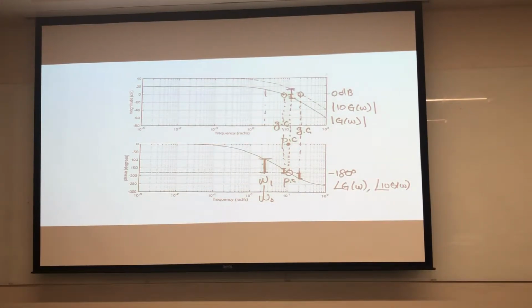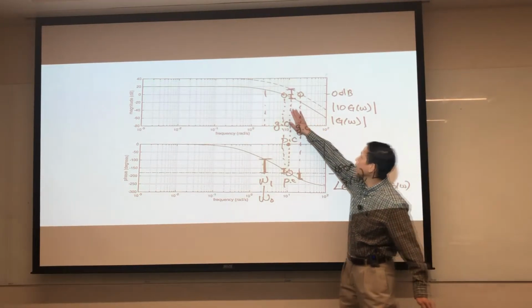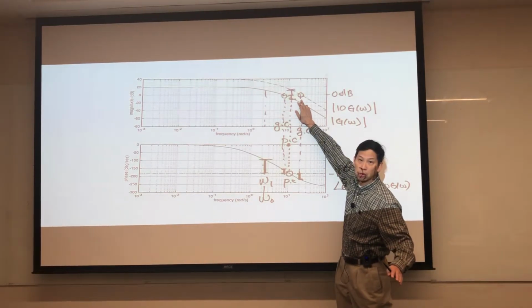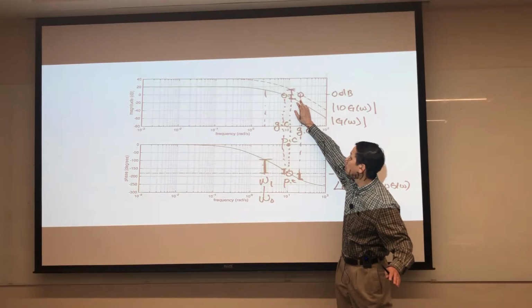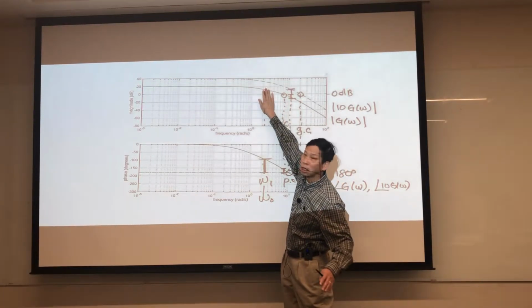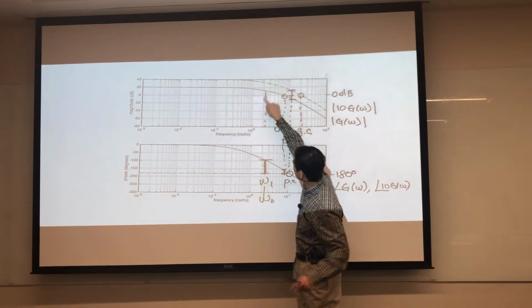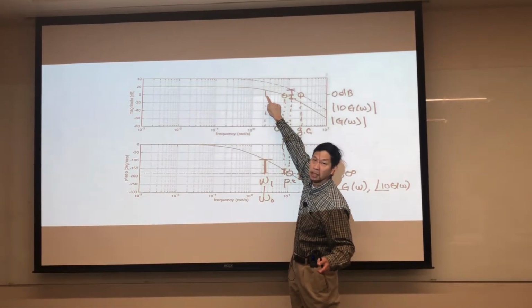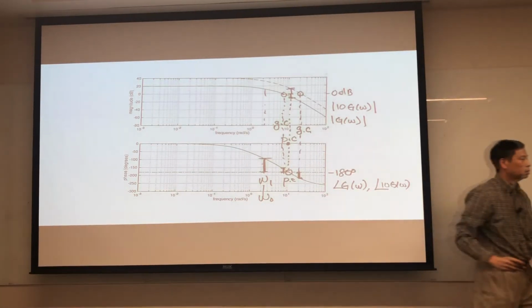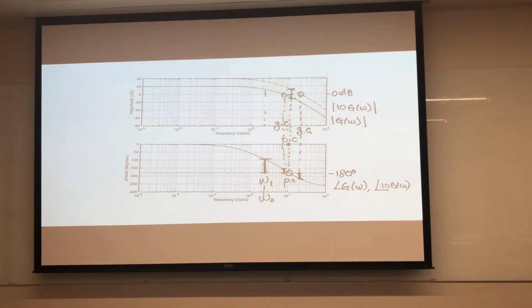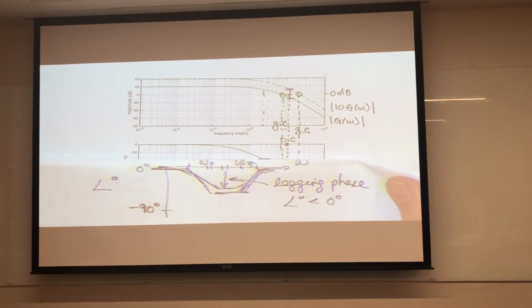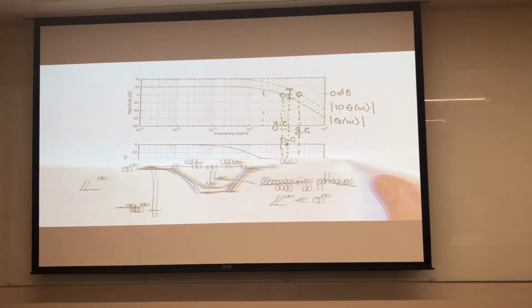Now the actual stability margins are not there though. They're not there because the gain crossover is actually occurring here before compensation. It occurs here with proportional control, but with phase lag control, I'm going to reshape the curve so that the curve goes through 0 dB right at that point. So that's our objective. We do this by picking omega p and omega z in a wise manner. When we put in omega p and omega z, it's going to cause a lag in the phase somewhere here.